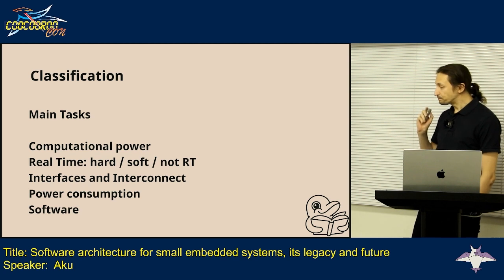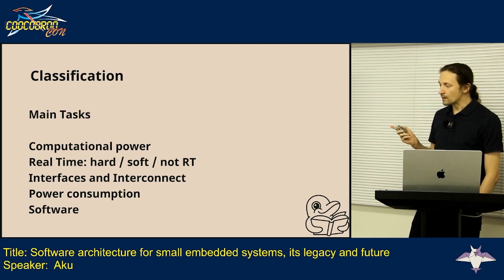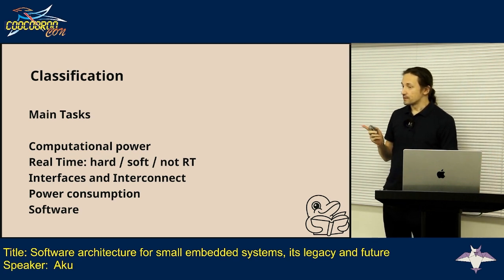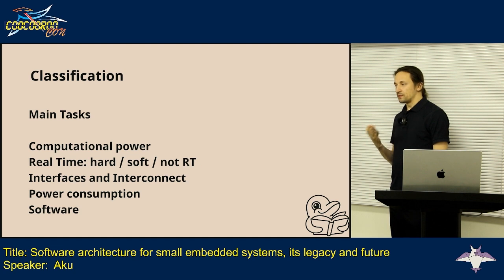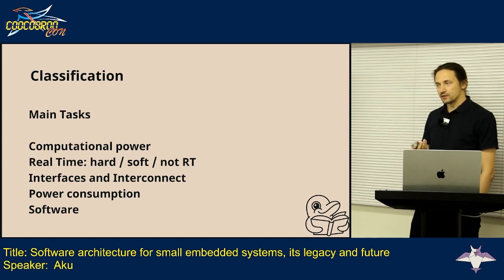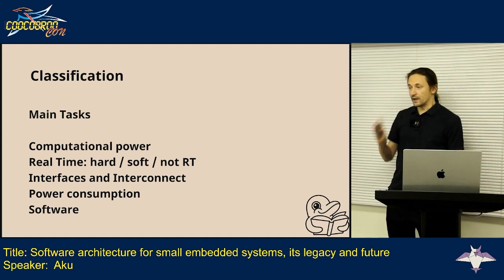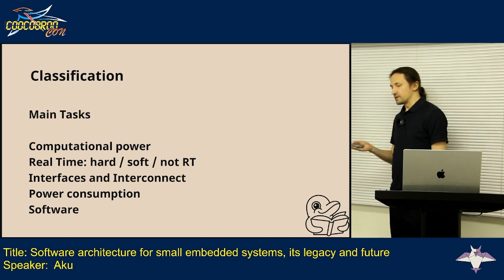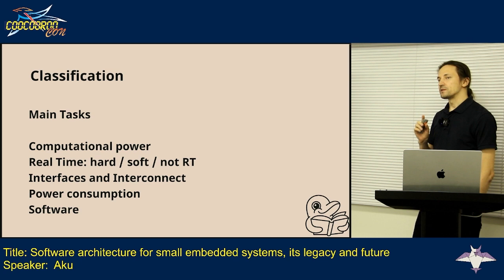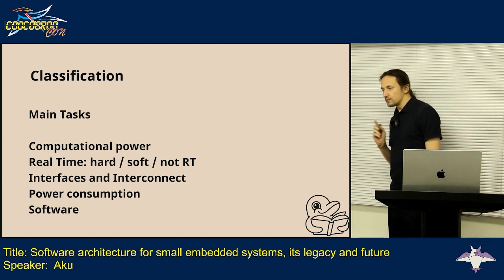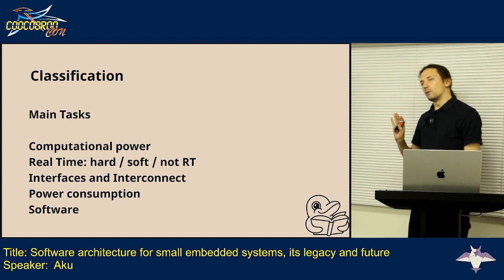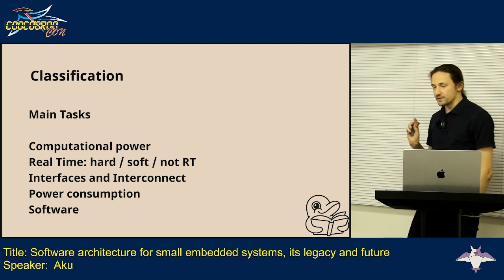Yeah, and obviously the software stack, because some MCU architectures are actually not that flexible. Let's say we have 8-bit architectures like AVR. Yes, you can write quite complex, sophisticated programs with it, but there are some limitations, and it will be a little bit more difficult to run a real-time operating system on it than, for example, on modern ARM cores.